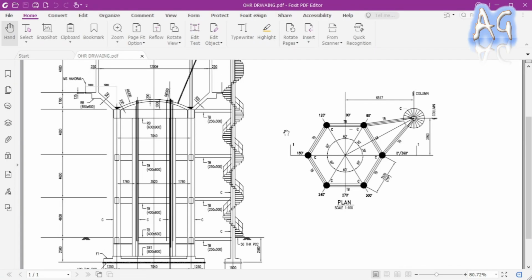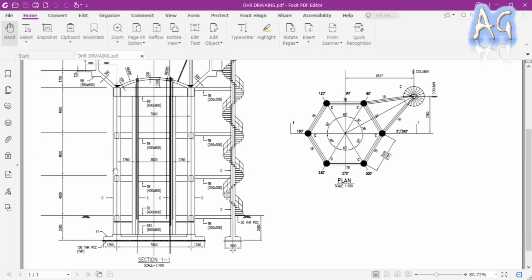Here you can see the column height is given. First the depth of foundation is given as 2.5 meter, and then the tie beams are connected at 4.6 meter distance, then 4.6 meter, and then 4.6 meter. Here the heel beam is situated. So the columns run from foundation to heel beam. This is the height of the column member, so I'm going to provide this height for the column member.